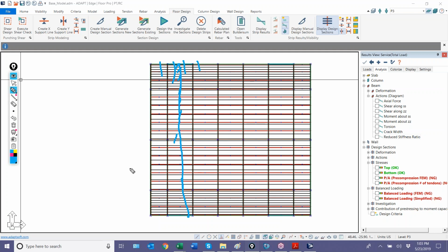I mentioned last week that the effective flange is just more of a way to create a uniform stress distribution over the beam flange. In essence, it's mainly used for an isolated beam design versus FEM. In the FEM model, we're already integrating over a non-uniform moment distribution for the flange. But yeah, you can use that option if needed.